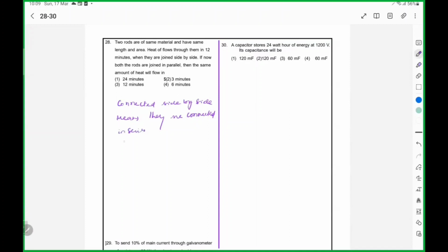So here, rate of flow of heat is Ka delta theta by L. dQ by dt is heat current. Temperature difference is the reason for flow of heat, which is L by Ka into H. It is like V equal to IR. This is heat current. This is temperature difference. Here resistance is L by K.